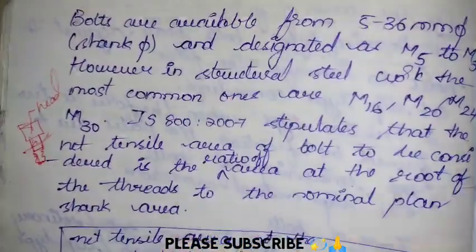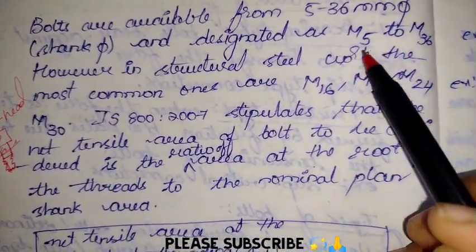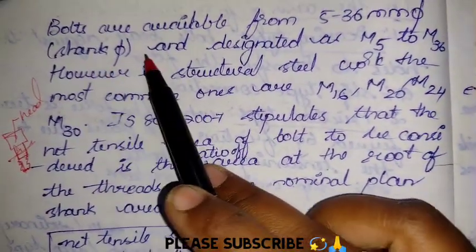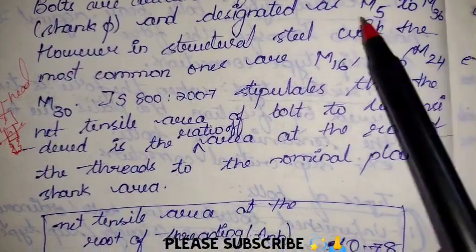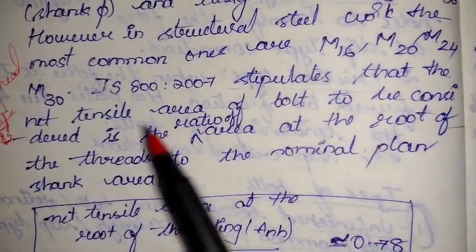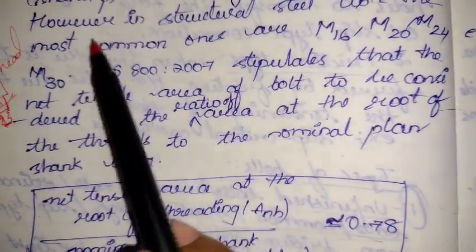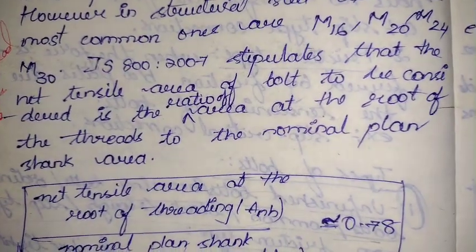Okay, this is the shank diameter, designated as M5 and M36. Here, 5 represents the shank diameter. However, in structural steel work, the most common ones are M16, M20, M24 and M30. IS 800:2007 is the code book from which we get the recommendations for steel structures.